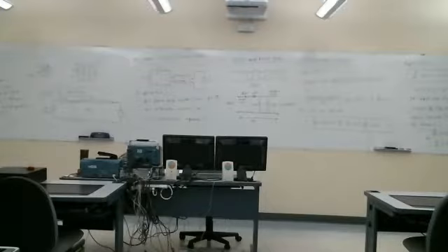That's an inductive impedance, j omega L. This is a capacitive susceptance. Susceptance is the reciprocal of impedance. The impedance of a capacitor is 1 over j omega C, so the susceptance is just j omega C, just like conductance is the reciprocal of resistance. Susceptance times voltage gives you current.